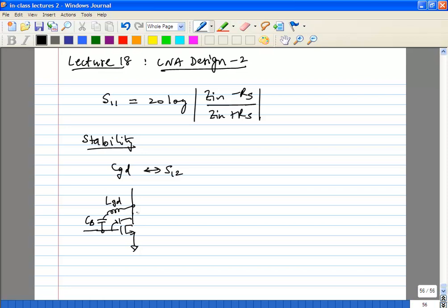The thing to remember is, obviously, as we know now, these inductors have parasitic capacitors. You have capacitors which have bottom plate capacitances, parasitic capacitances. So all of this will load your input node. And obviously the second thing is, we're not even talking about the area, right? So you saw that it's 200 microns by 200 microns. It's just huge. You can't just afford to add an inductor any time you want. So this is the first way: tune out your CGD.